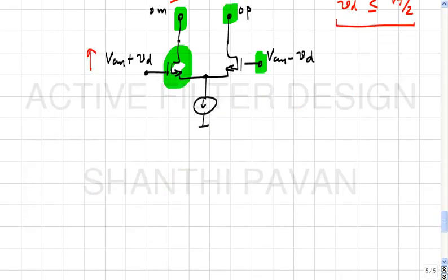And this is somewhat of a pessimistic limit also, because you are expecting the drain and the gate to be 180 degrees out of phase, which usually doesn't happen at all nodes. Okay. Now the next thing I'd like to point out